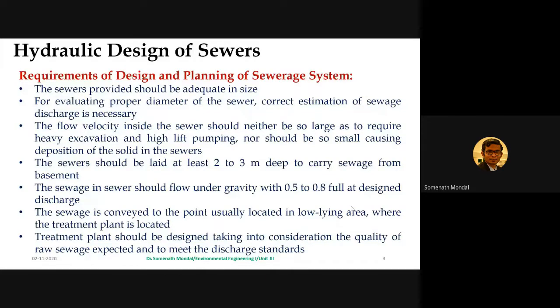But running a pump with such a huge volume of sewage is not always economical, and it will make the entire system uneconomical, and it will be difficult for the municipality or the authority to run it for a longer time period. And that is why we need to consider this. At the same time, the flow velocity should not be so high that it can cause wear of the pipe material. So that is another aspect.